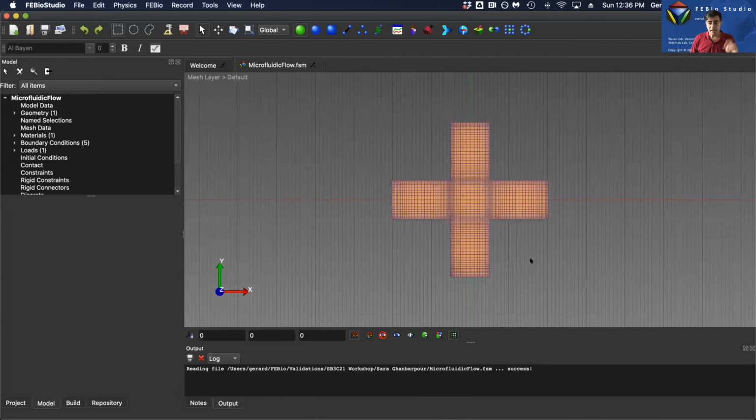However, the problem that you have is that this dimension is a millimeter, and from here to the center is 2 millimeters, but you have a particle that's only 25 micron in radius. So even if you wanted to create a finite element mesh, it would be a very difficult problem to solve because of the disparity in the scales. So this would be more suitably done using what we would call a multi-scale analysis. But the problem is not trivial, and it can be done partly.